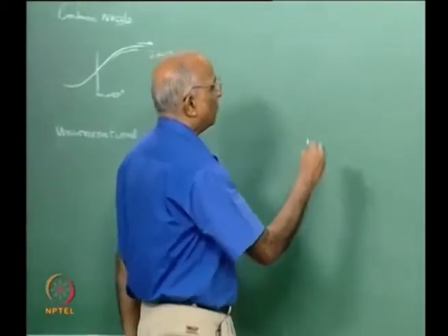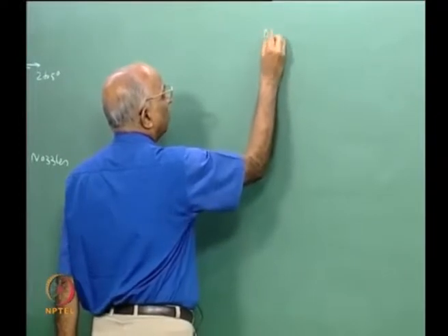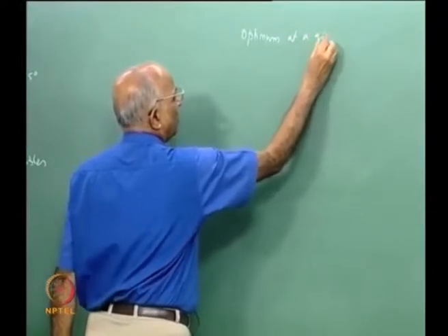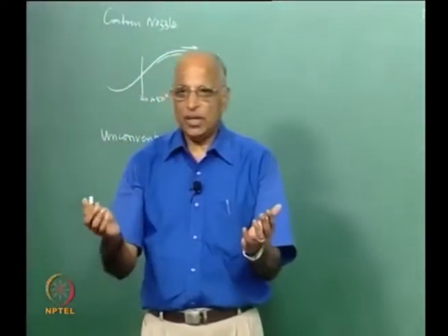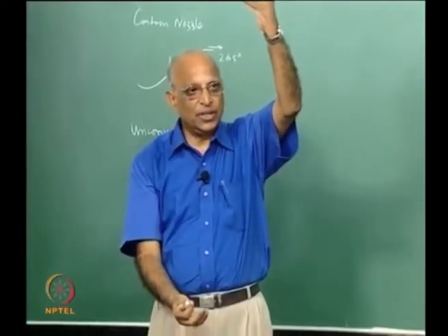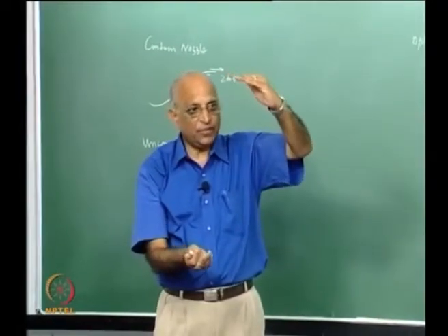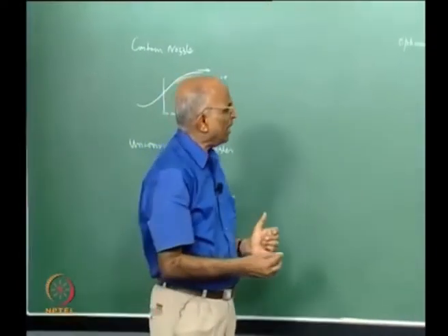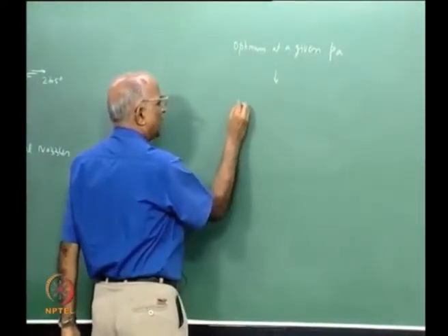First I can tell myself, well, a nozzle operates at its optimum at a given value of ambient pressure. In other words, if I want to make a nozzle, I design it for, let us say, 15 kilometers, start operating it from 0 kilometers, and the rocket goes up to 30 kilometers. Initially 0 to 15 it is not optimum, at 15 it is optimum, beyond 15 again it is under expanded and not optimum. Therefore, can I have something like an extendable nozzle.